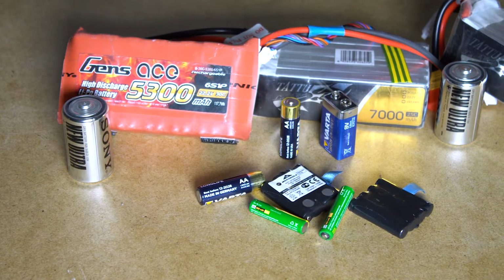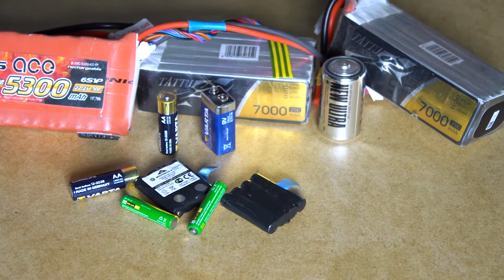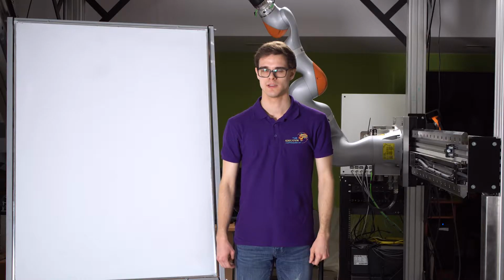We often deal with portable voltage sources, such as batteries. An important parameter for them is their capacity expressed in ampere hours. A battery with 1 ampere hour capacity will work for 1 hour with 1 ampere before it discharges. The same battery may give you 2 amperes for 30 minutes or 100 milliamperes for 10 hours. Now we can move on to the most popular sources used in everyday life.